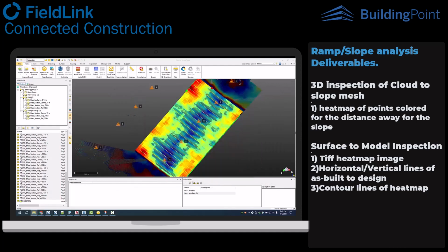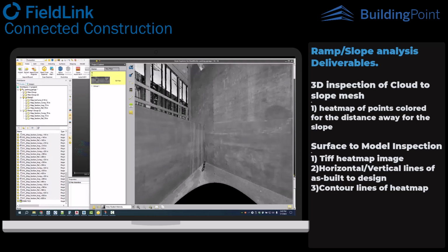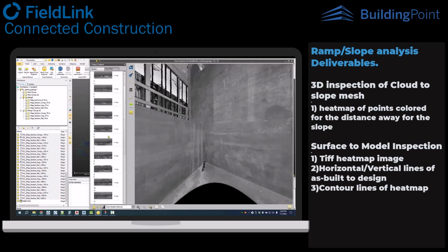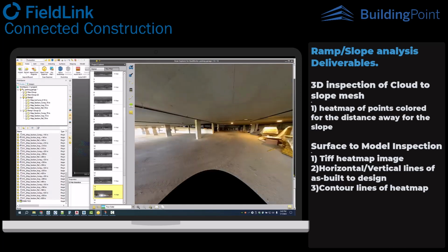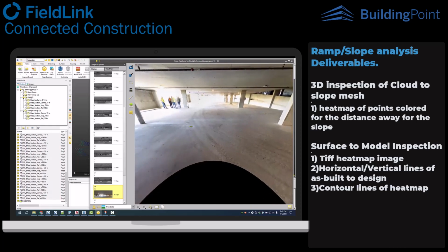You can do every line like we did here, or you can do particular lines if you just need to show, let's say, every 10 feet rather than every 70 inches. It allows you to, I don't want to say skirt by local anomalies, but like what you saw here and what you can see if I look at the actual collection of the data, like dirt and stuff, you may not want to clean this all up, but you can run your line so you're not including that.